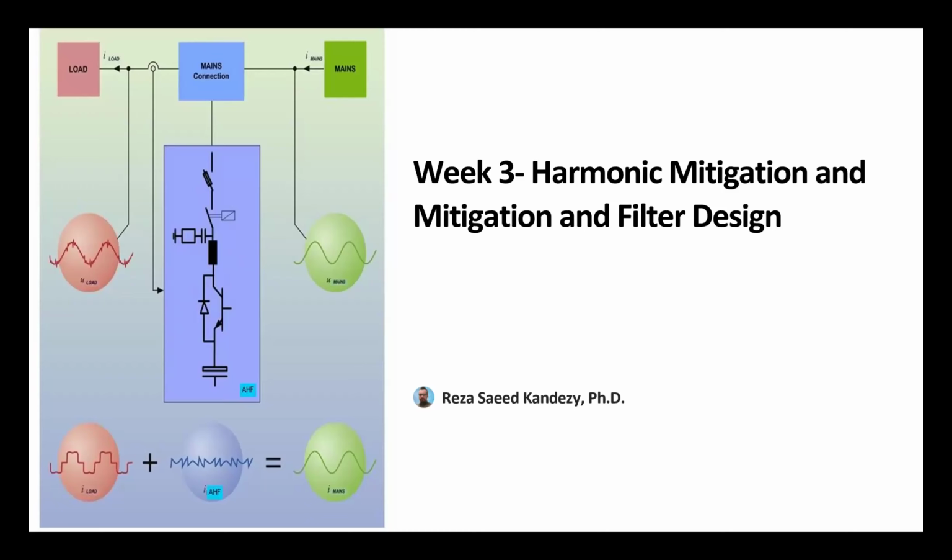We learned about pulse width modulation, or PWM, and we said this is the main strategy when we talk about inverters and control of their switching. We learned about the sinusoidal PWM, where we had a reference signal, which was a pure sinusoidal or desired waveform in a power system.